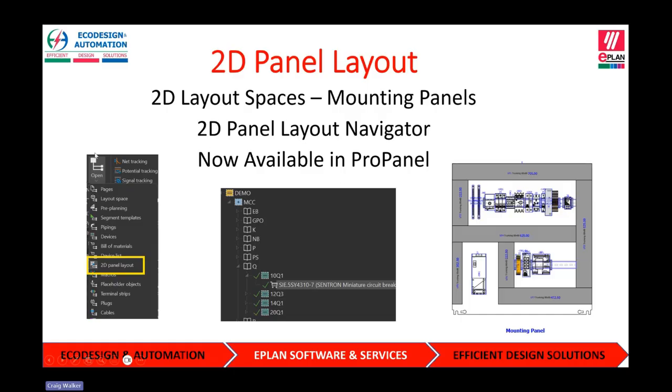Obviously, under the navigators, you can see the 2D panel layout navigator. You can actually use the 2D panel layout navigator to check off devices as you place them in your 2D panel layouts. It's got mounting panel layouts just like P8, and it can generate enclosure legends from those, and you can cross-reference and jump back and forward from them as well.